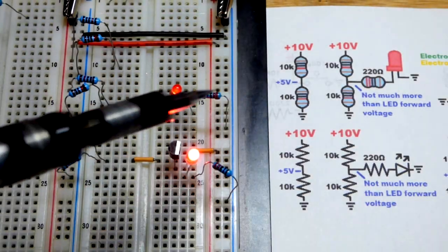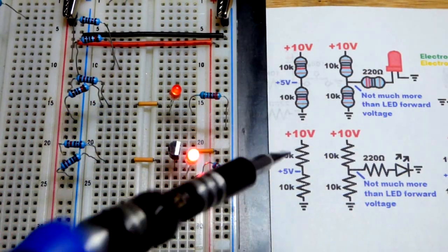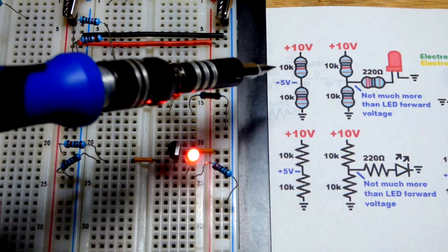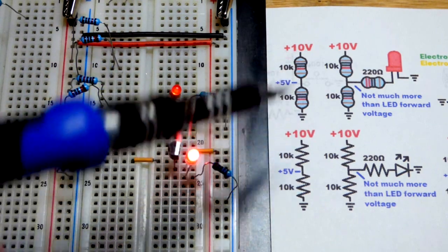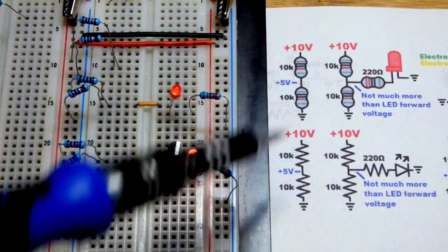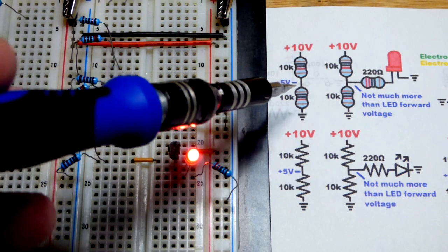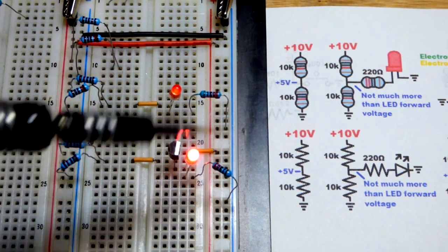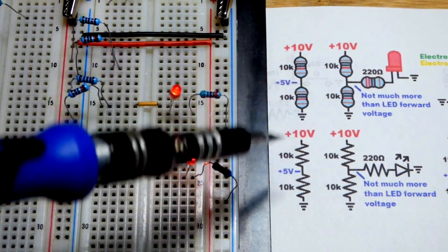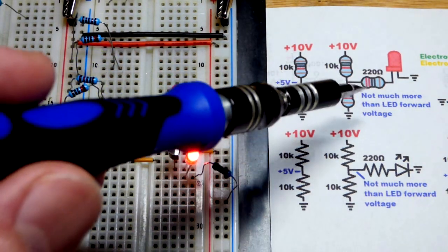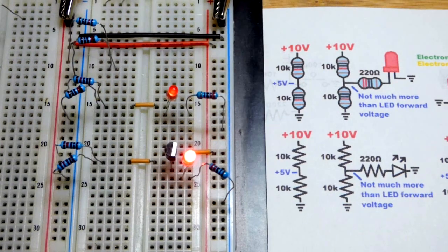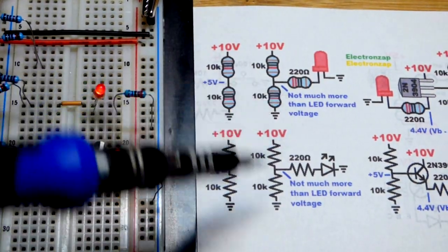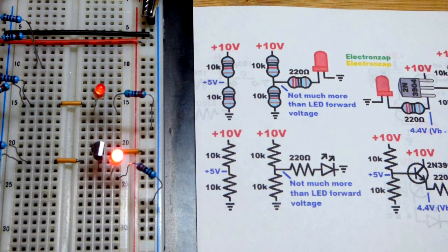So now in this video we're going to come back to the fixed resistor voltage divider. If you have two equal value resistors, you put them across a power supply, you're going to have half of the voltage right where they connect between the resistors there. So this is just a signal voltage though. You can't power something that needs any real current because the voltage will drop.